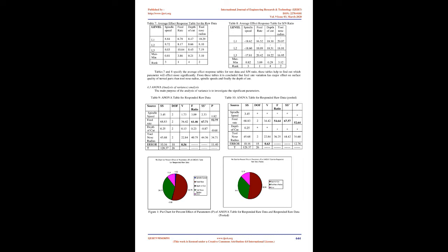It has FANUC control system. Its make is Takisawa of TPS 3100 series. Rake angle of cutting tool is 0°. Front clearance angle, primary, is 10°. Front clearance angle, secondary, is 12°. Point angle is 90°. Shape of cutting tool insert is triangular. 3 cutting tool inserts of different tool nose radius of 0.4 mm, 0.6 mm, and 0.8 mm were used during experimentation.